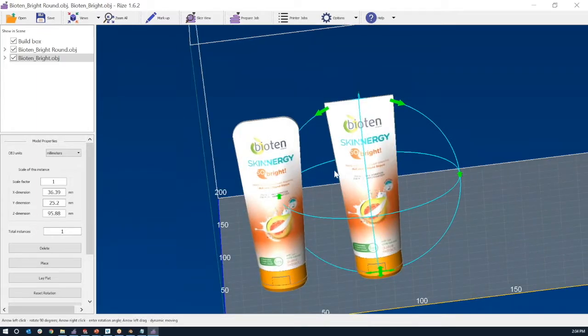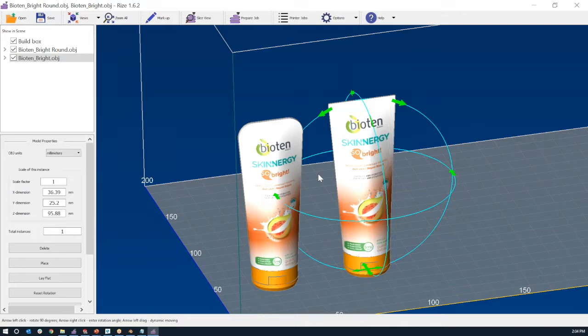Both of these are referencing the same MTL file, and the MTL file is of course referencing the same image file. So this is a way of, in some cases, taking a large number of slight variations of a single part and mapping all of your OBJs to a single MTL so that you don't need a huge mass of files to keep things connected.